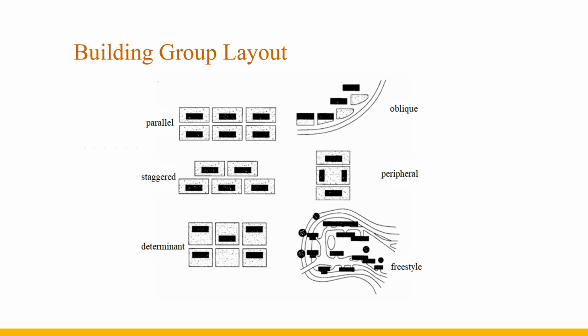Building height, length, and depth also have a great impact on natural ventilation. Buildings with different geometric shapes form different vortex airs in different wind directions. The location and size of the opening in the room are related to whether a certain airflow velocity can be obtained in the room and whether the indoor flow field is uniform.